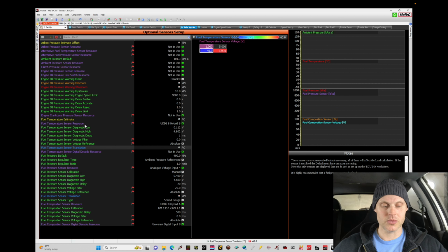and we're gonna find in this case, taking a look down here, the fuel temp translation table. This is going to be set to the configuration for a GM Continental style sensor, pretty much the standard for ethanol content sensors that are on the market. We're going to find the table actually should be 1 volt and then 5 volt. And then at 1 volt, it's -40 Celsius, and at 5 volts, it's 125 Celsius.